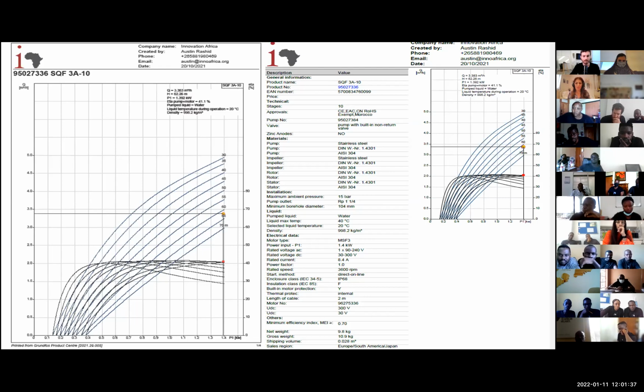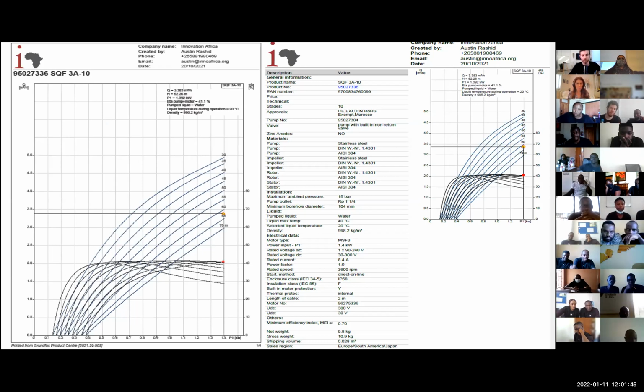And you can see the working point, the nominal point that you already filled in, which also shows me the flow rate, the power I need to supply with the solar panels, and the TDH. On the left side, you see the pump, just like we mentioned. And on the right side, I can see the specification of the pump, which is very important for the electrical engineer to look at. So we will know what the current, the voltage, and the power are that I need for the pump to work in the best way without damaging it.